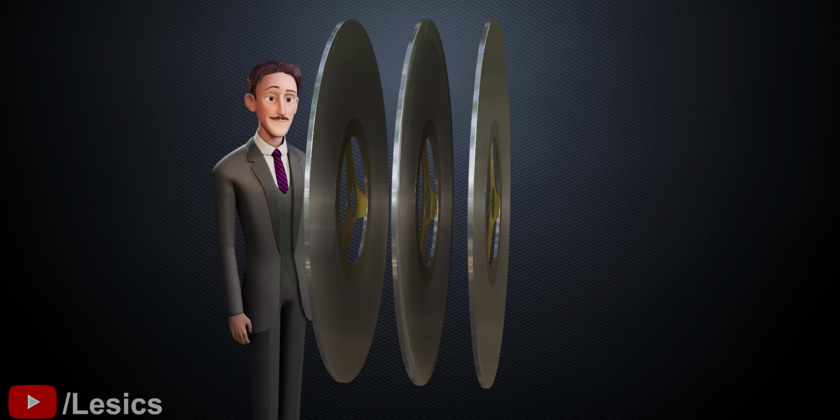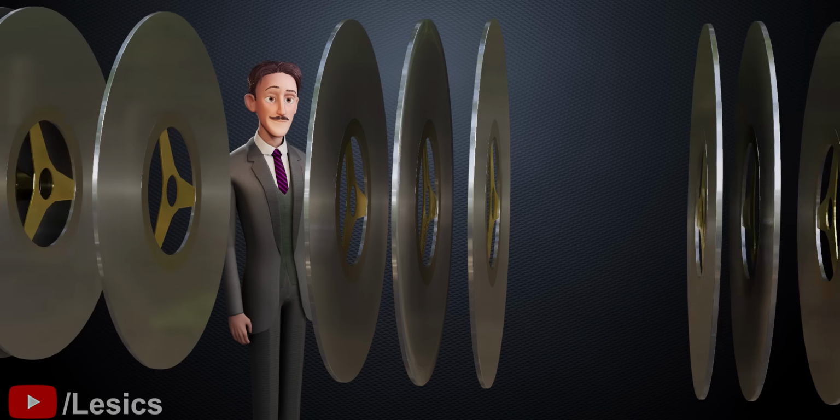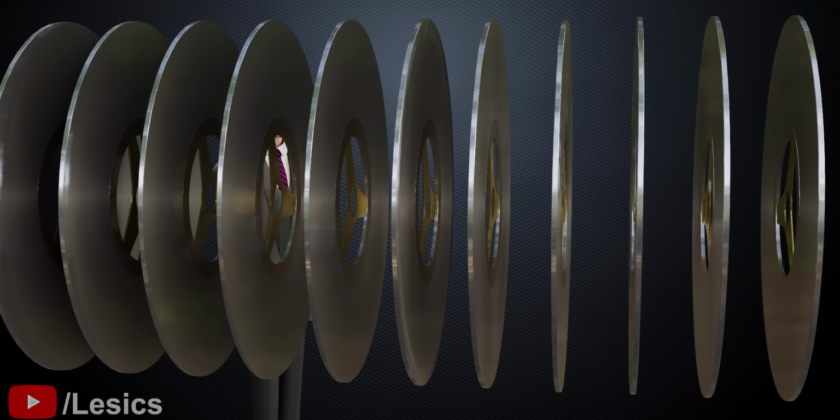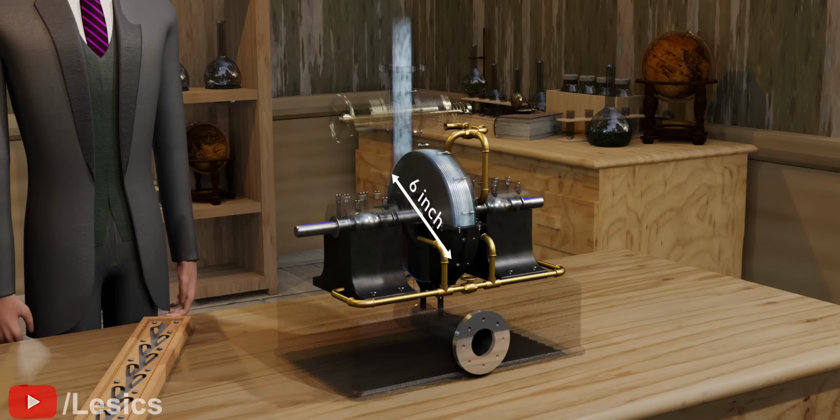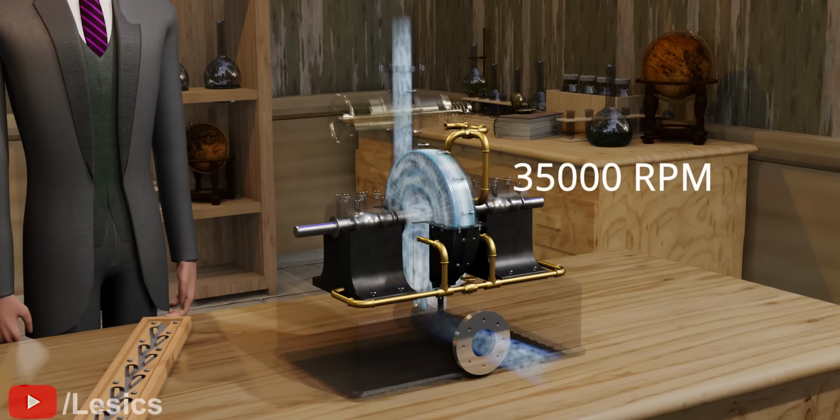Tesla found that by increasing the effective area between disk and fluid, the turbine can produce more torque. So he added more disks. This model had a diameter of 6 inches. However, this design failed horribly. The issue was that this turbine would run at a very high speed, 35,000 RPM.